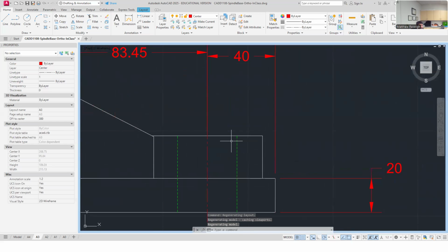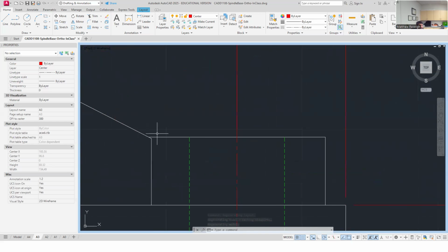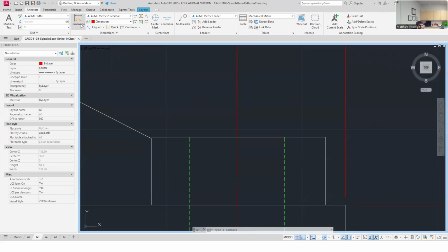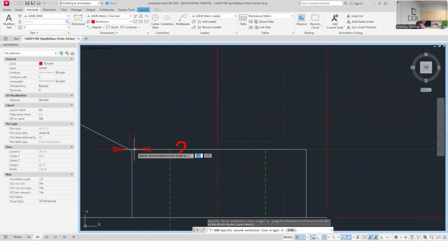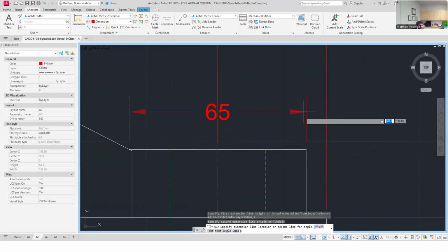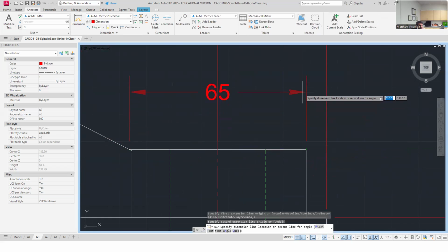I can get its rectangular size right here, at least the outer diameter. So I think I'm going to move over here to dimension its diameter in the rectangular view. And that only applies if it's a circular part. If it's a radius part, I don't put its diameter in its rectangular view. Its radius would be called out in its view where it looks as a radius.